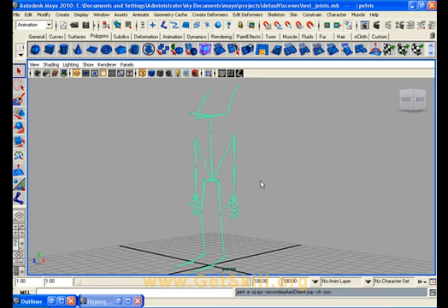But remember one thing: the automatic orientation of the joints is not always perfect, depending on how your skeleton was built. It can flip orient. It can flip certain local rotation axes, and you need to manually fix those pivot points.